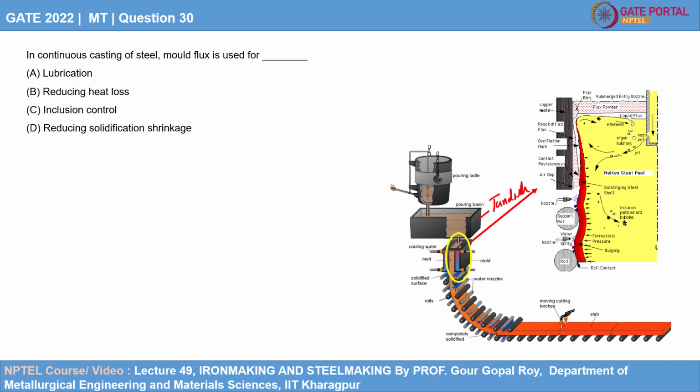Here, the entrance of the mold is filled with the inert gas to prevent the reaction of molten steel with gases in the environment like oxygen. Here, the molten metal will move swiftly through the mold and it does not completely solidify in the mold itself. This entire mold is cooled with water that flows along the outer surface. So you can see this is the cooling water channel in, out. And typically the steel casting generally solidifies along the walls of the casting, and then it generally moves to the interior of the steel casting.